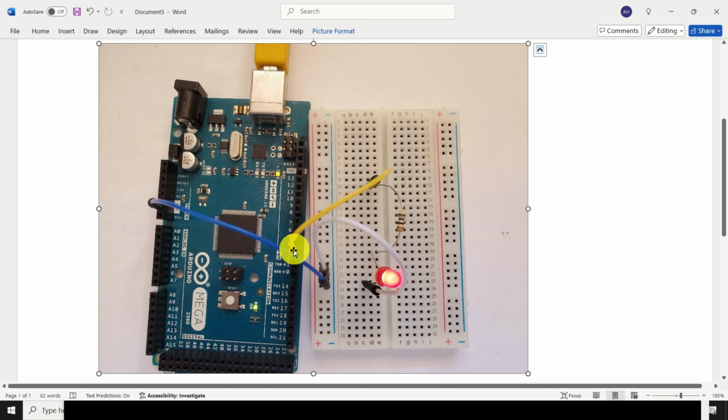That is, we will send input signals to the pin 3. These input signals will be on or off, that is high voltage or low voltage. In fact, the high voltage will be, I think, 5 volts. Once the 5 volts is sent over here, we will close the circuit and the current will flow and it will light this diode. Then when we send low to this pin 3, or when we send 0 volts, the current will become 0 and this LED will not shine.